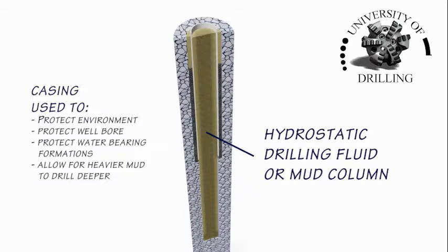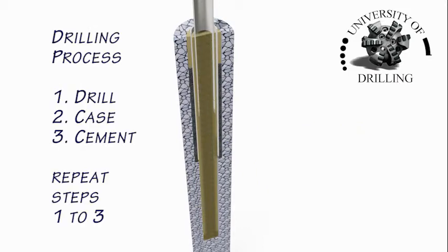and the drilling mud for making new hole in deeper formations must also be heavier, and hence casing is placed to protect the shallower rock formations from the mud weight needed to drill deeper formations, and from the pressures within deeper formations that could, if released into a shallower formation, cause an underground blowout that could waste valuable hydrocarbons or which could pollute, for example, groundwater formations.